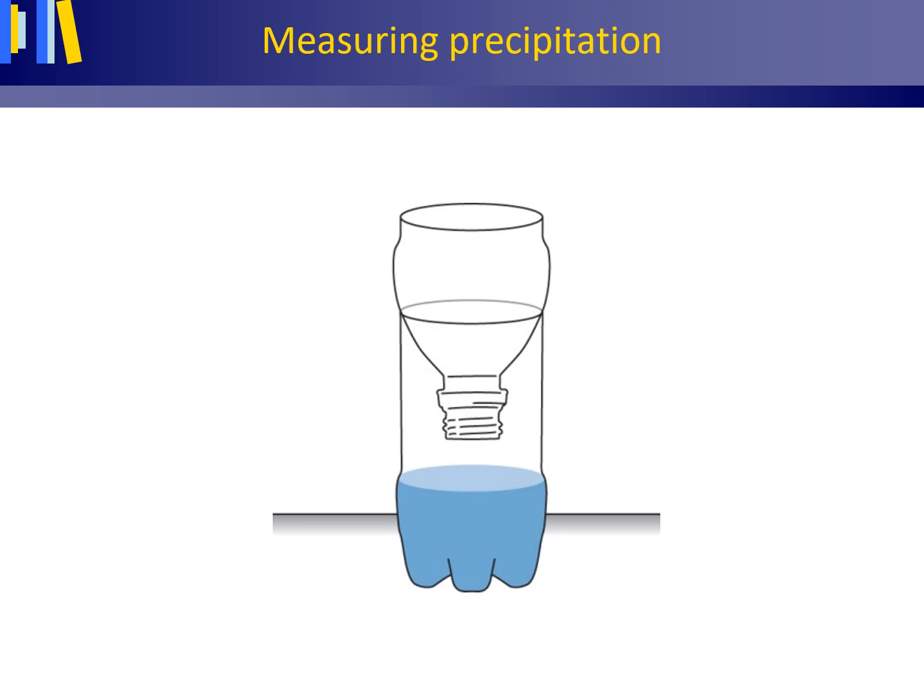in cubic centimeters, which, by the way, is the same as milliliters. Simply divide the volume of rainfall in cubic centimeters by the surface of catch of the orifice in squared centimeters, and multiply this result by 10 to obtain the rainfall depth in millimeters.